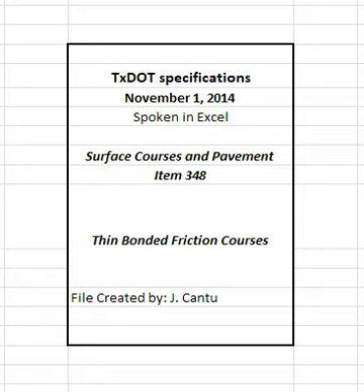4.9.3 Membrane. Obtain a 1 QT sample of the membrane material for each sublot. Obtain the sample from the spray bar on the paver. Label the can with the corresponding lot number, and deliver the sample to the engineer. The engineer may also obtain independent samples. If the engineer chooses to obtain an independent sample, the engineer will split a sample of the membrane with the contractor. The engineer will test at least one membrane sample per project to verify specification compliance.